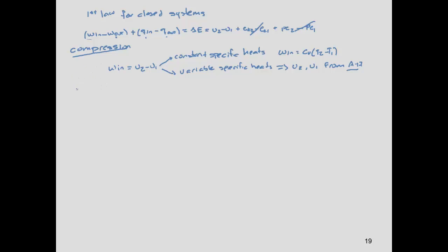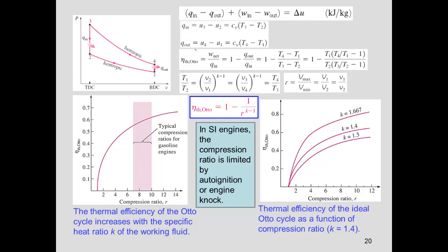we can compute the heat addition process. In this process, we don't have any work in or work out, because it's a constant volume. We have Q in. Obviously, we don't have any Q out. And then the final state is U3 minus U1. Same consideration as here. If we repeat the analysis, we can get these expressions. Q out will be the difference of U4 minus U1.